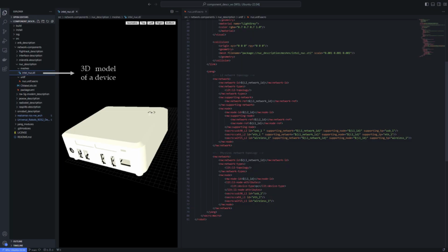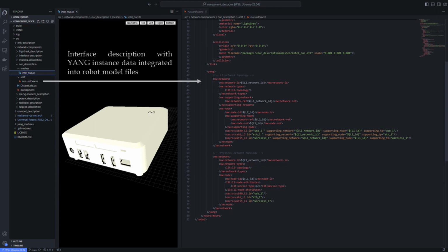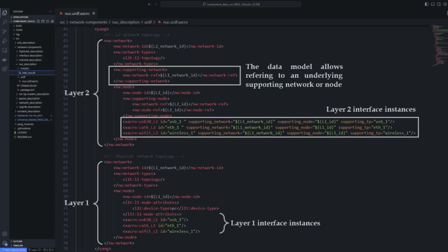Generally, these description files contain the 3D model of a device. With our extension, these are able to represent the communication interfaces with the relevant properties. This layered extension aligns with RFC 8944, which is intended to define a YANG data model for Layer 2 network topology. After modifying this model with attributes for this field of application, it can handle connections between defined nodes, link them and show the connection properties of the complete robot system.